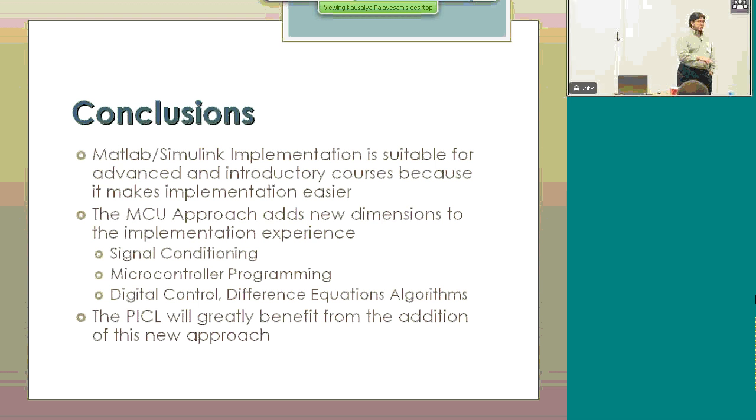We're starting to do this. We did this with 2 students in an undergraduate research project. But the idea is that they understand the difference between designing directly in the Z transform domain, or in the Z plane, versus designing first in the continuous domain and transforming to the Z domain. The idea is that you will need a higher sampling rate for that to work, and in the vocabulary of the students, it's an overkill, right?